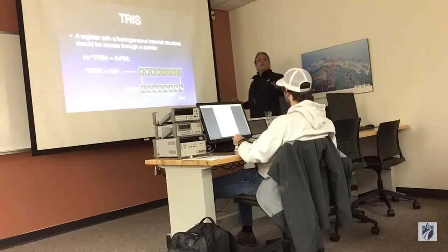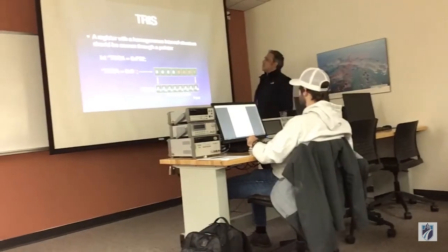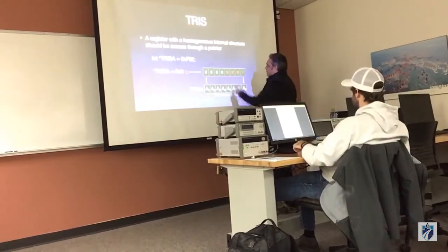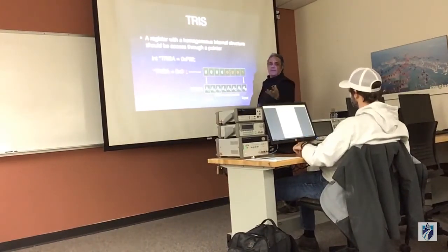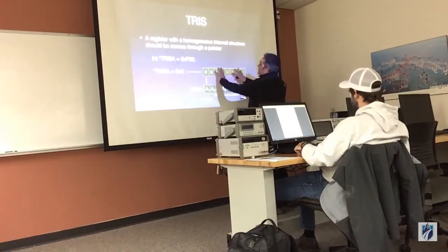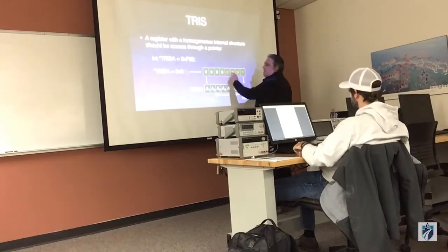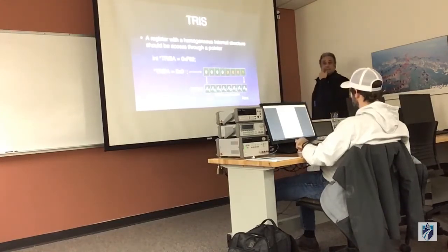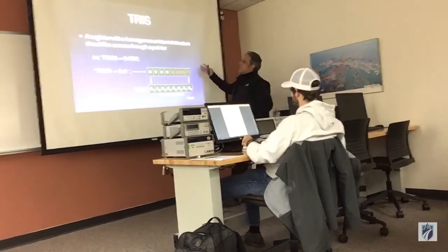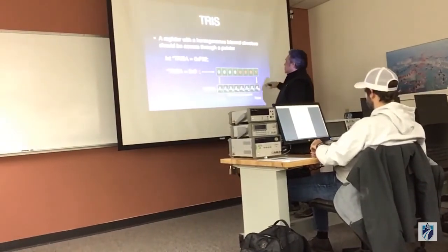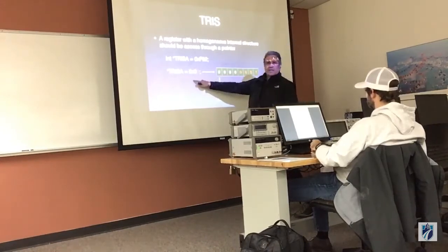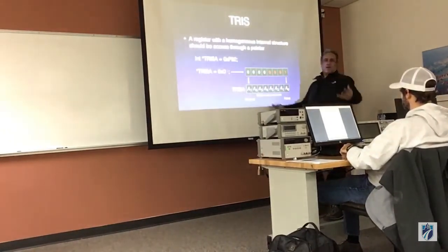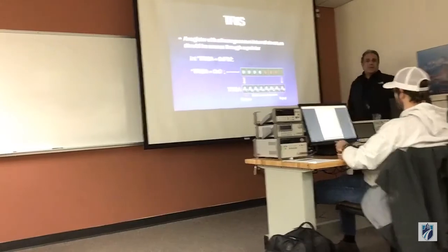Correct. You could set an OR if you want to. Let's say that I just want to change the behavior of only that pin. You could use bit masking to avoid changing the behavior of anybody else but the pin that I want. Yes. In this case, because I just want to make sure that I get everybody a startup value, like in your setup, I want to get started somehow. Then I set it up this way.